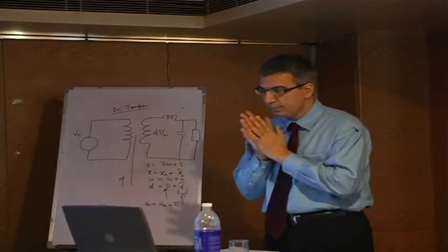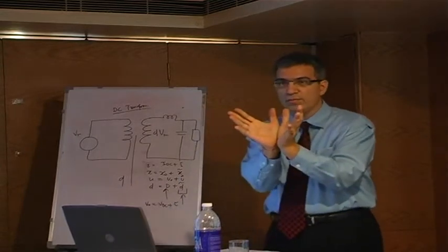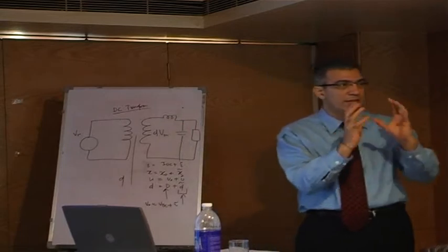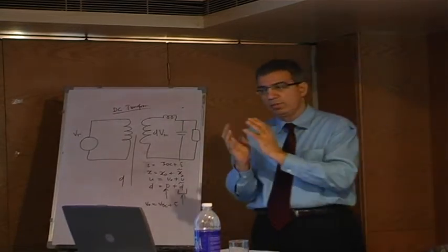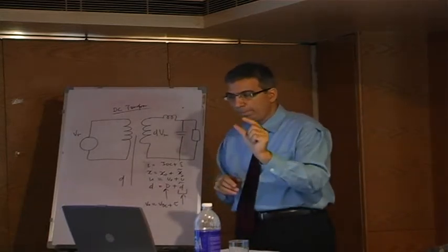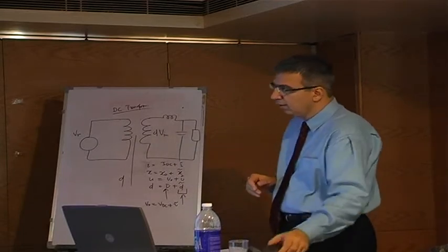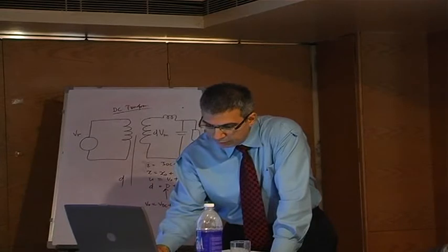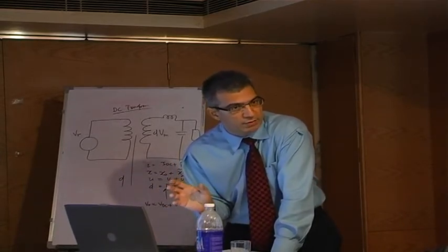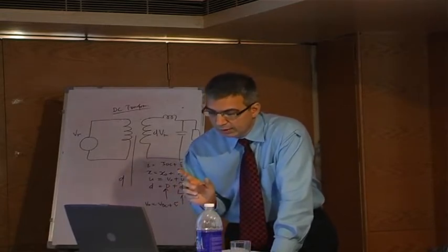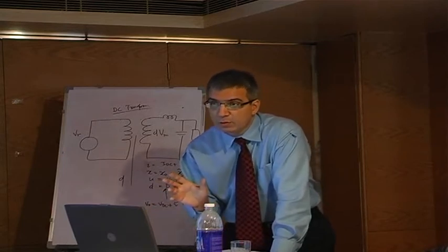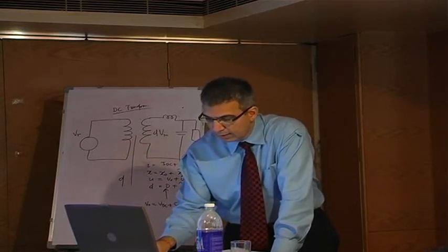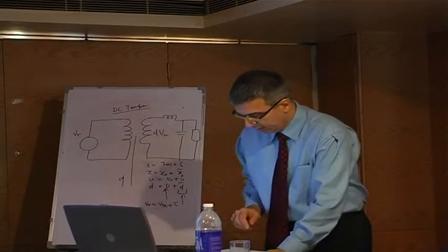And this simpler model essentially says, okay, I want to have a model which is not circuit variant. If my circuit components change, if I have parasitics, this particular switching element model does not change with circuit elements. So the point I want to make is it looks very similar to the state variable equations. It looks similar to it, but the good part about it is that it is independent of circuit elements, right? But the basic fundamentals are exactly the same, and let me write the equation for you on that one.